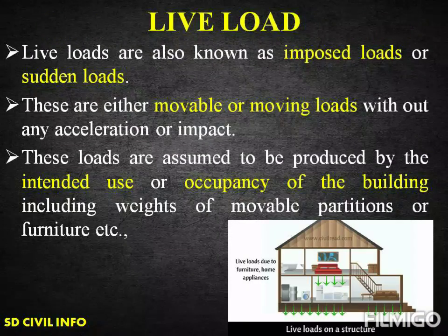Next one is live loads. What are live loads? Live loads are also known as imposed loads or sudden loads. These are either movable or moving loads without any acceleration or impact, and these loads are assumed to be produced by the intended use or occupancy of the building that includes weight of movable partitions or furniture, etc.